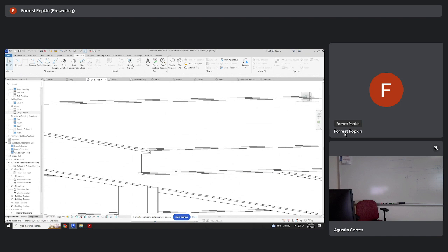I'm not expecting you guys to know how many gusset plates you need, where the bolted connections need to go, but the expectation would be if I ask for a typical column connection drawing, you at least know how to put the pieces together and show me what that could look like. Any questions about that?